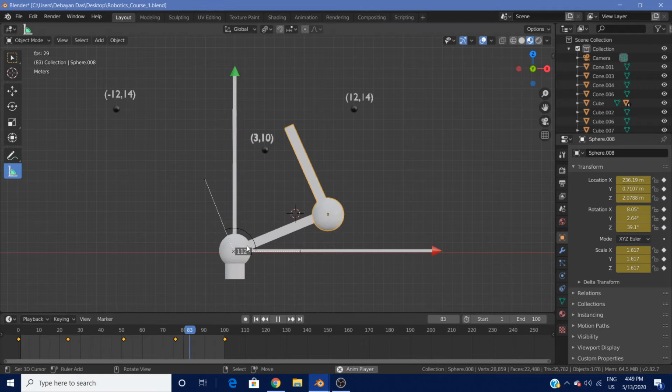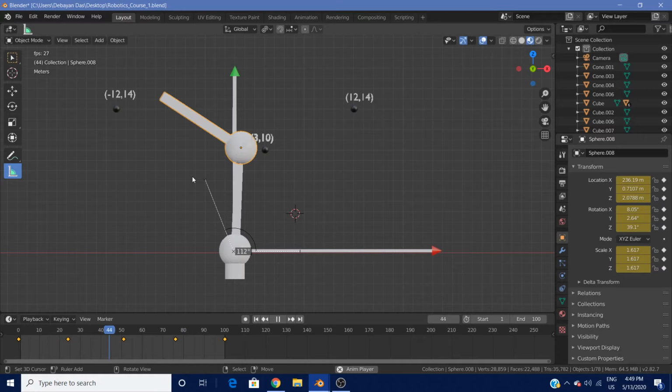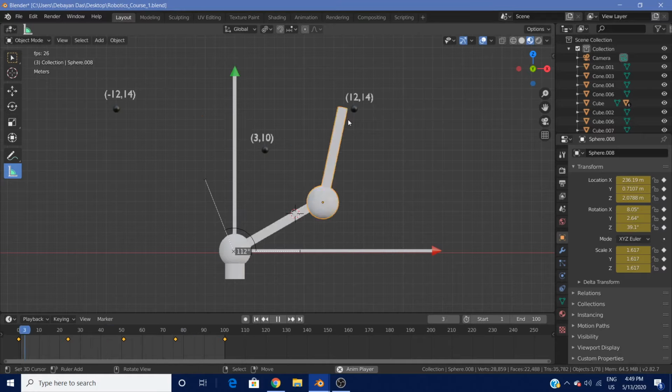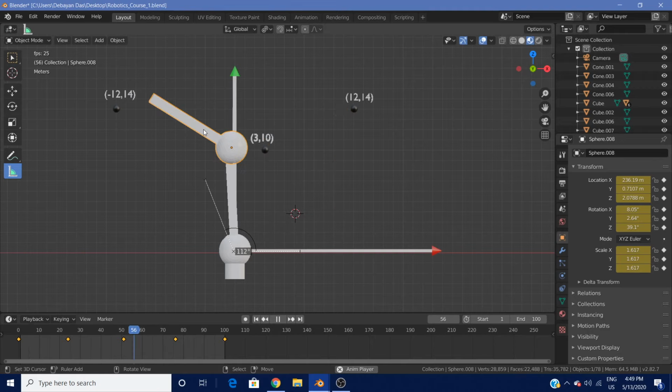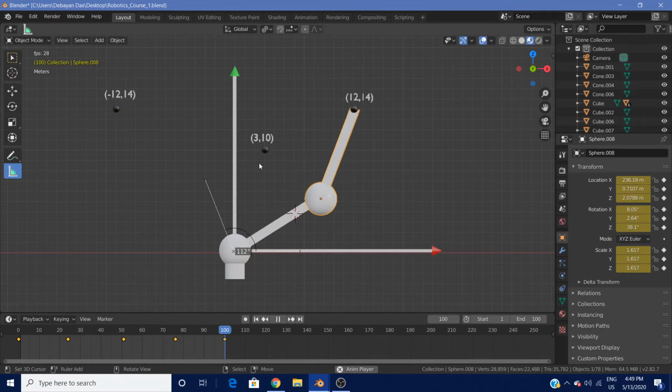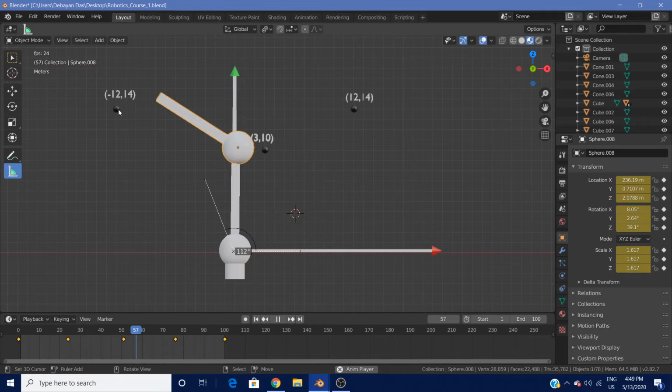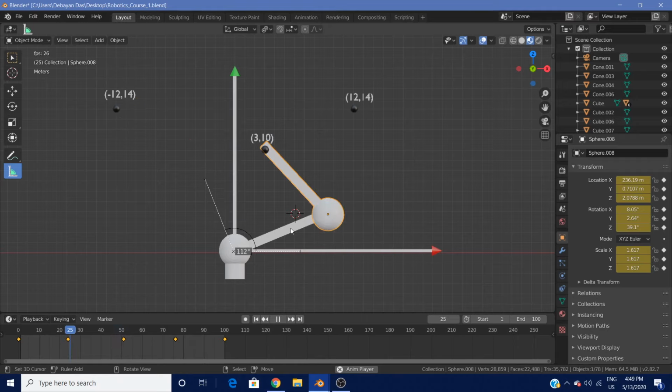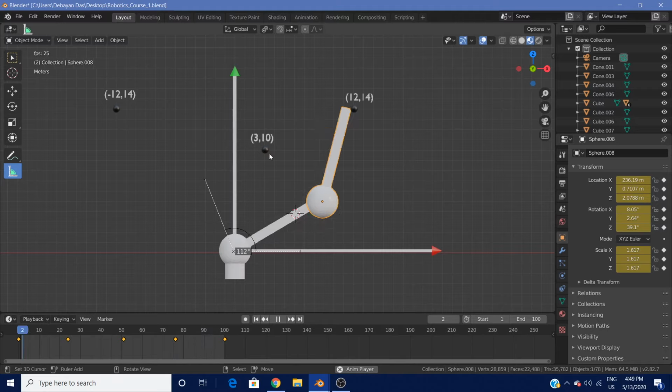Theta is always changing values at the same speed from this point to this point, and the same speed from this point to this point. There are two different speeds, but it's the same within each area. And you can see that there is a region of almost infinite acceleration, because right here, as it switches direction, there has to be an infinite acceleration for it to switch direction, which is not possible for a normal motor. It would also cause a high torque, and our robot might just topple over.